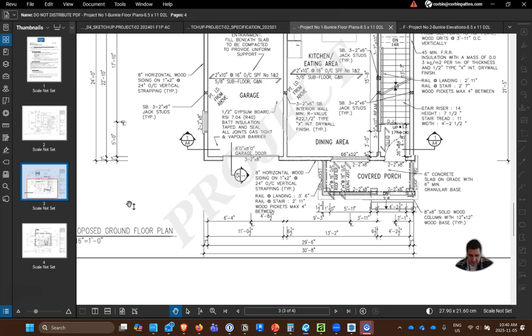That doesn't make any sense, to be honest with you. But so we have a 7-inch thick wall, really 8 inches, so 6'4" plus 7 is 7'1". So 7'1" to the center of the door from the outside of the wall. Following the math. And the reason why we give center of door openings is because we're trying to show intent. We want to show that we want the door to be centered in a certain location.